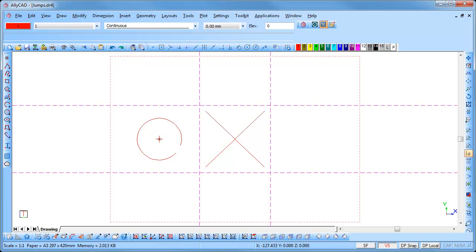Press the I key and the cursor will jump to the nearest geometry intersection. This will only jump to geometry intersections, not to intersections between other entities or between other entities and geometry lines. Press the 0 key and the cursor jumps to intersections between two solid entities or solid entities and geometry entities, whichever is the nearest. It will not jump to the intersection between two geometry entities.